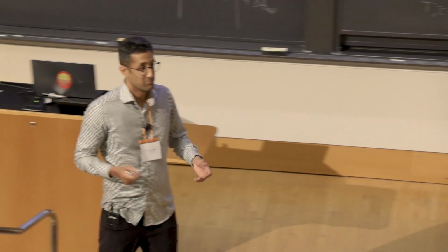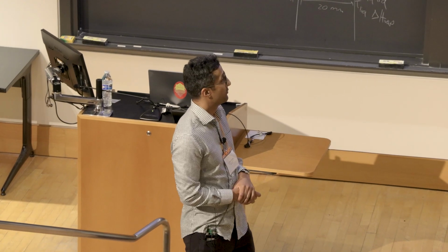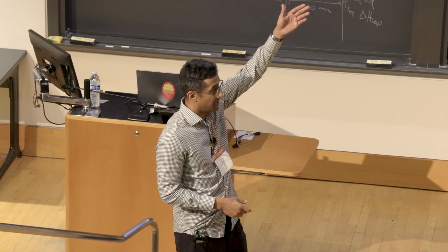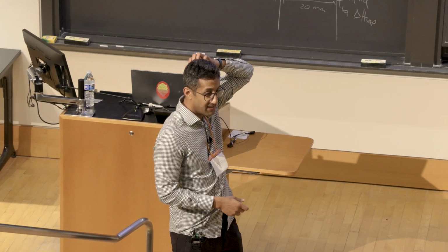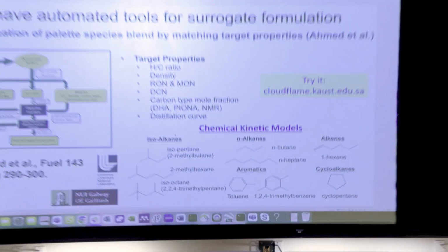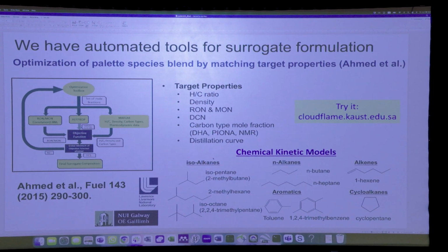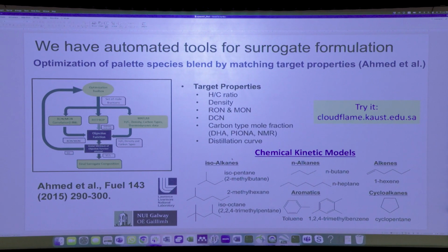And we identified a mixture with cyclopentane, isooctane, another molecule shown here called triptane, and other things to meet the 540 rule, to maximize the octane numbers, the heating value, which is very important, and so on.